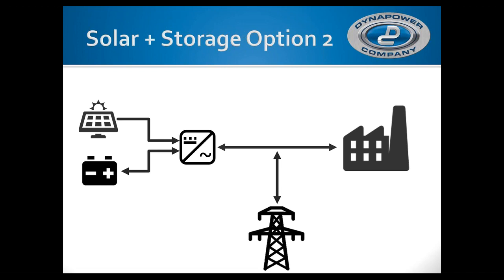Obviously, one of the disadvantages here is that you're ripping out a perfectly good PV inverter. The advantage is that you have consolidated controls and built-in islanding capability. And again, this is an option. Typically, our experience has been that if we're going into a new project where we know it's going to be battery plus PV, this is the topology that we would typically recommend and that we've seen others use as well. But again, if we're doing a retrofit project, it's a choice, one or the other.